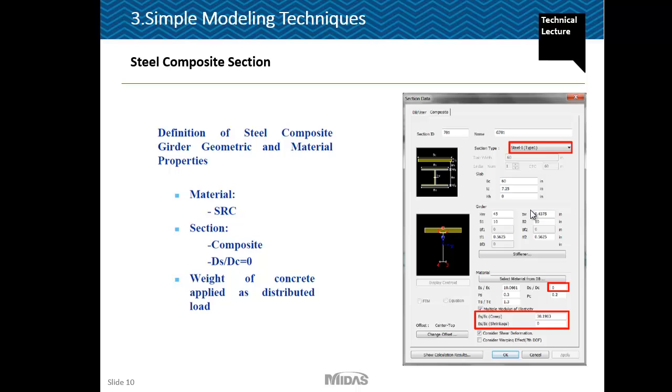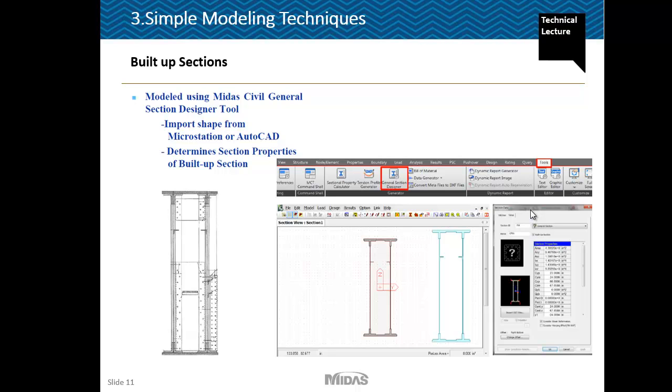And then defining the section, again we have a dedicated section tab which allows you to define different types of sections. In this case, if you see, we have steel composite section type which allows you to define the slab and girder separately, and also allows you to define the modular ratio to be considered for the calculation purpose. And talking about the sections, we have again a set of database depending upon the steel section properties that is available with the codes.